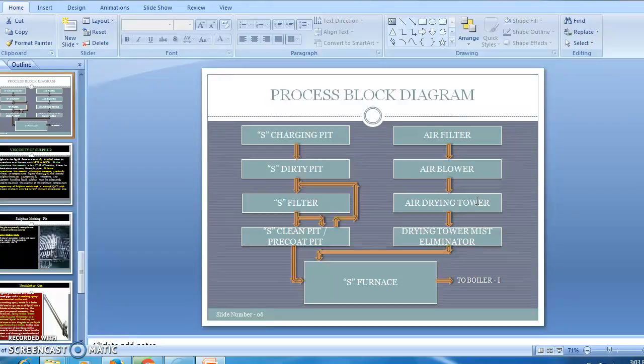So you need to remove that sulfuric acid mist, which is done in a mist eliminator. It's a type of filter which removes mist, which is normally small droplets, whereas the air can go out, and it goes to a sulfur furnace where you contact sulfur, which is in liquid form, and oxygen, in the form of air in gaseous form. Air is supplied in excess to make sure that the sulfur is completely oxidized. So it is actually a complete reaction.